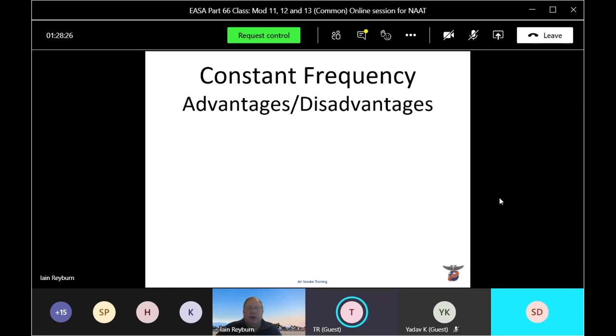Is the opening and closing of the bus tie breaker automatic or just manual? Automatic. What senses the 200 feet height that causes it to close? That comes from your radalt. The only accurate measurement is from the radalt. Okay, thank you.